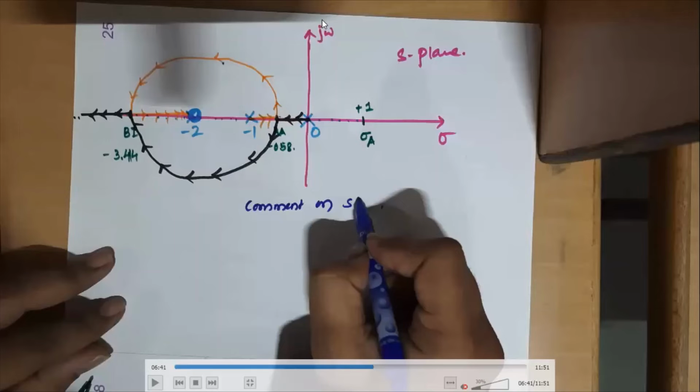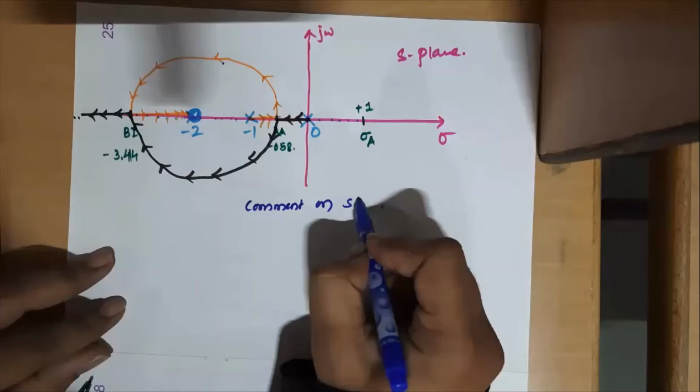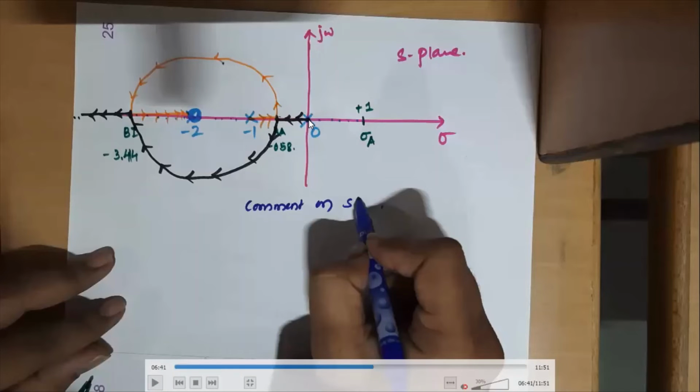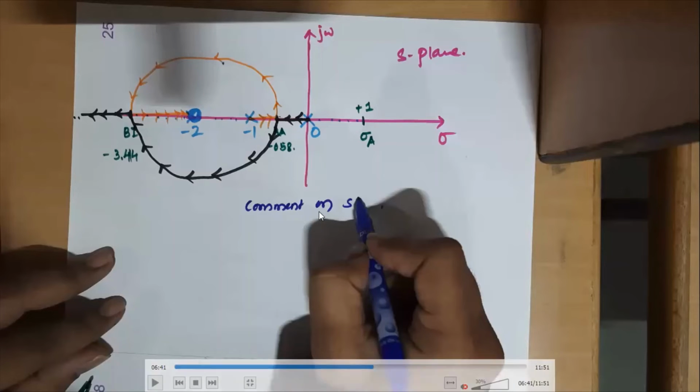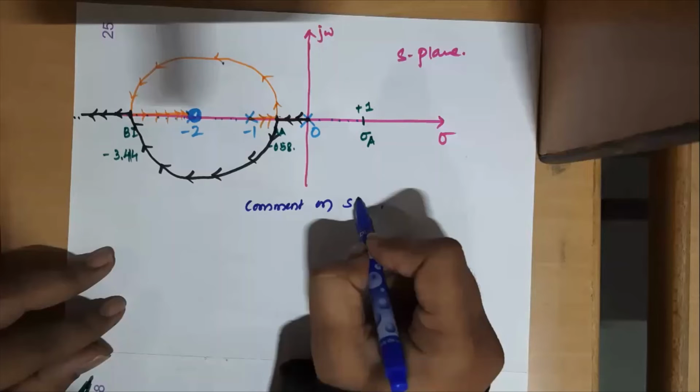So this is actually a case of asymptotically stable. It is not critically stable because whoever said it is critically stable, you definitely have looked at only this pole location, and you forgot that for k equal to 0, it is moving to the stable region. But it is always better to mention clearly. I mean, don't just write the comment that this is asymptotically stable. Fine, but better mention for the safer side as